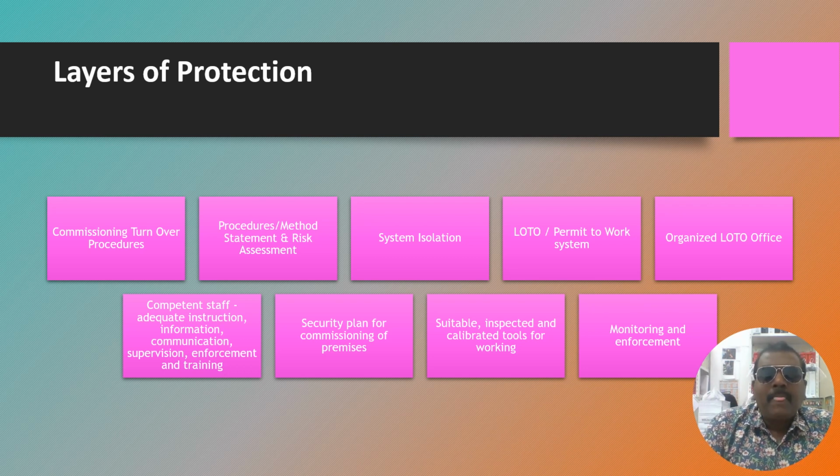Maybe after locking it, what happens? They issue the work permit. The team members can go and do the alignment. Once the alignment has been completed, they can close the work permit so that this padlock and the tag can be removed from that particular breaker. So now it's ready to check. Next they can go ahead for the heat run test at the site.